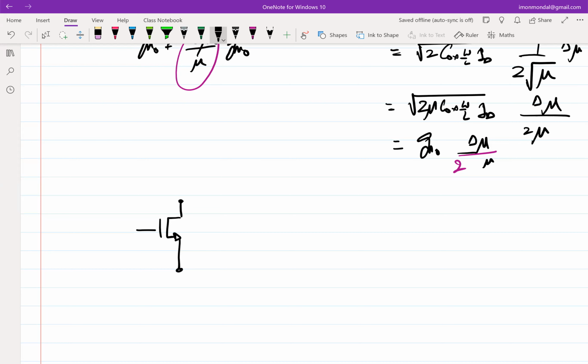Do you agree? Till now, we have kept the source voltage constant, grounded, but that need not necessarily be the case. So I can either affect the gate voltage or affect the source voltage, and in terms of pushing current in or out of a transistor, I can push current into the drain or pull current out of the source. So it seems like there are 4 possible combinations, right?